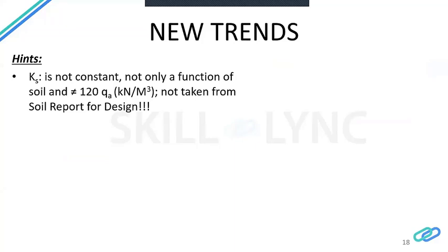This is not relevant at all. You remember when we talked about the averaging technique and that it might be fatal? Well, in most cases, at best, the soil reports, especially in this region, depend on the averaging technique, and they are not project relevant.